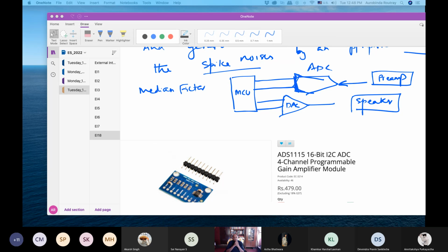But suppose you have only one port. So how will you give 16 bits to the DAC? You have to do it in 2 clock cycles by latching it properly. Think about it. All of you, please think about it. If you have any questions here, you ask. I am here to discuss.